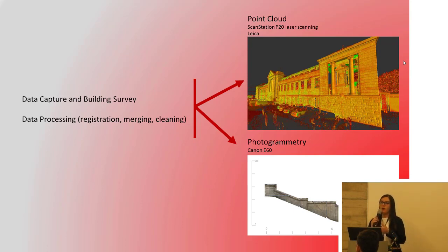But when you are talking about an existing building, and especially a listed one, everyone has specific details about, I don't know, columns, capitals, and if the client is requiring a high level of accuracy and detail, we are talking about level 4, for instance, you have to represent exactly that kind of column, that kind of capital. So you need to create that kind of element from scratch to be more accurate and to deliver a very, very high level of detail in terms of respecting what the client is demanding.